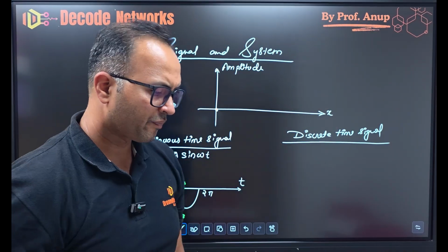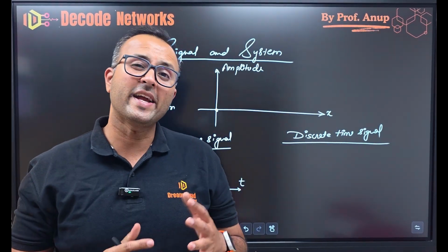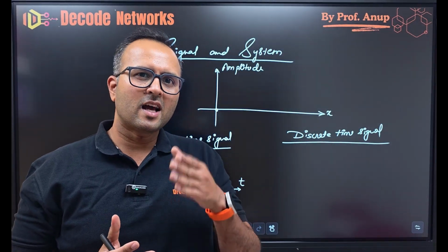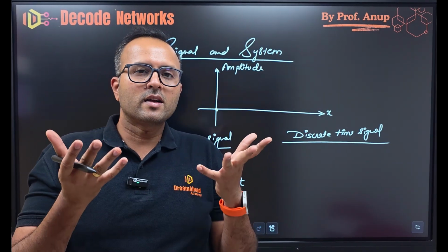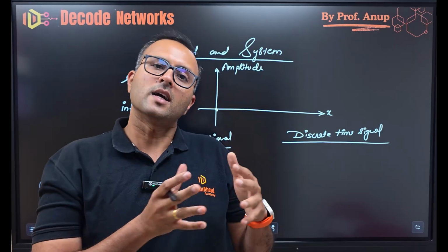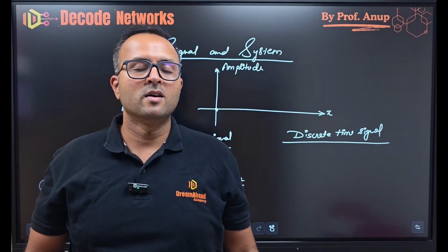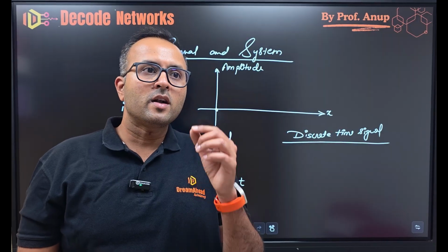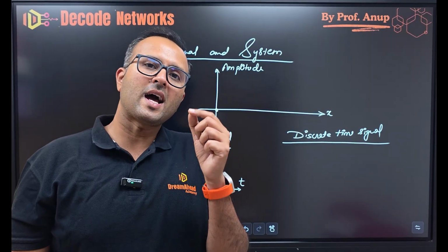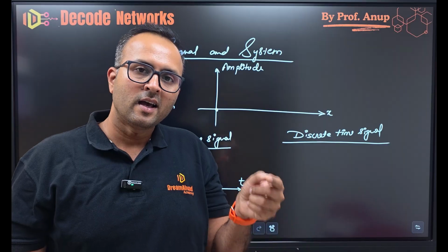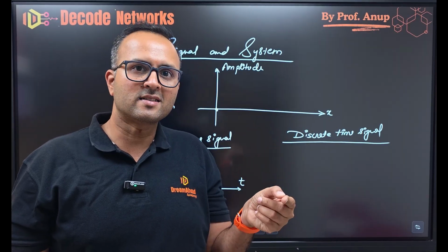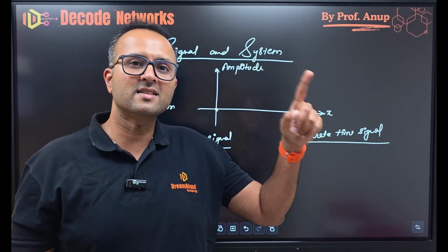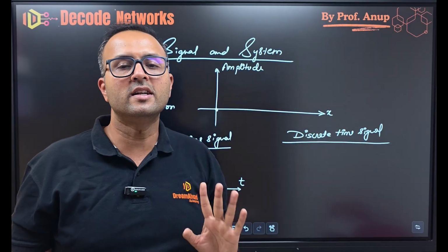Now we have heard something about ADC. What exactly is ADC? Analog to digital converter. Simple, we think that there is an analog signal which gets converted. Now, what is the process? The process for this is sampling, right? Sampling is where you make your analog signal discrete, and then that signal gets quantized, giving you a digital signal.